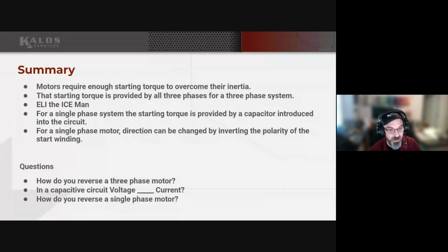But there are motors actually that have start and run capacitors. And the difference basically is just that the start capacitor is taken out of the circuit after the system is running. But then there is a run capacitor that is left in the circuit, and they're going to be different designs. In the video we watched, he mentioned how an electrolytic capacitor might be used for the start winding, and unfortunately, I'm not educated as to what it's called, but it'd be some different variant of a capacitor than what you would have on that start winding.